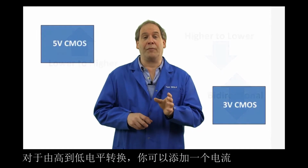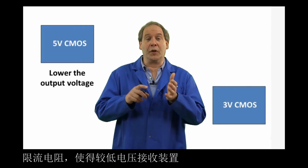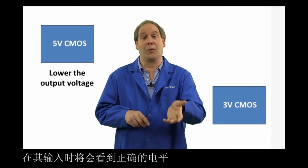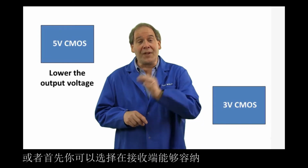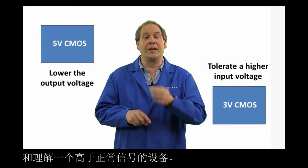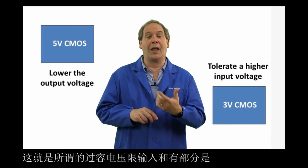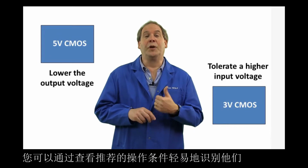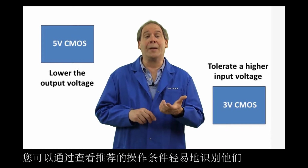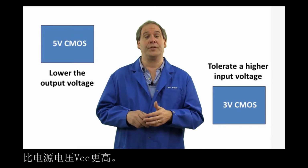For high to low level shifting, you can make the outputs of the sending side weaker simply by adding a current limiting resistor so that the lower voltage receiving device will see the correct level at its inputs. Or you can pick a device on the receiving side that can tolerate and understand a higher than normal signal in the first place. This is known as overvoltage tolerant inputs, and there are parts in virtually every logic family that can support this. You can easily identify these by looking at the recommended operating conditions and look if VI can go higher than the supply voltage of VCC.